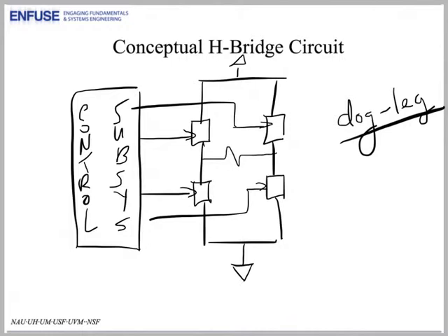Our control system needs to operate the two doglegs of the H-bridge as follows. Now we've addressed this before, so we can go over it fairly quickly. But remember that we want in one half of the AC output the current to be flowing through this path, and in the other to flow through this path. But notice the key idea here is that we have two doglegs. Here's one dogleg, here's the other, and we want to alternately activate one and deactivate the other.